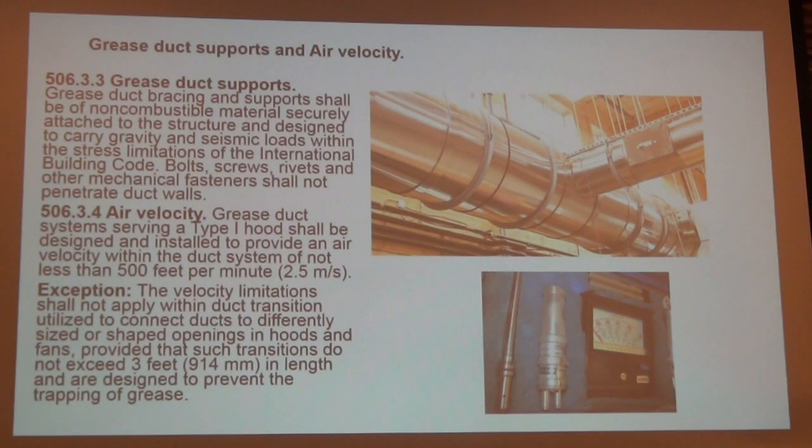The second one was to reduce the stack effect so that all your heat would not be sucked out of the appliance when you have a windy day or whatever. And the third one was if you do have a bad draft, it comes out of the diverter and not down where the burner's at, so it doesn't blow the pilot out or cause the flames to shoot out the bottom of the appliance. So that was the reason why we have diverters.